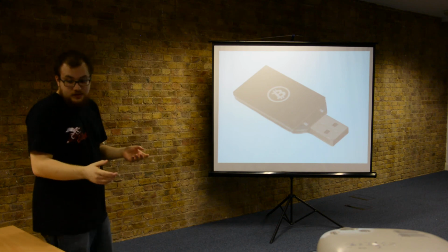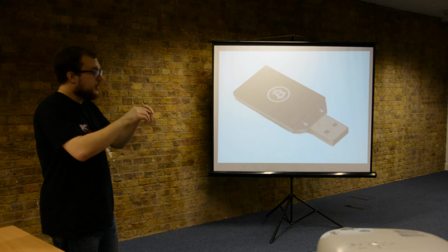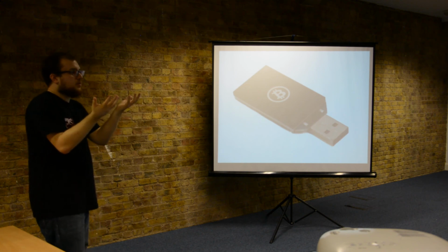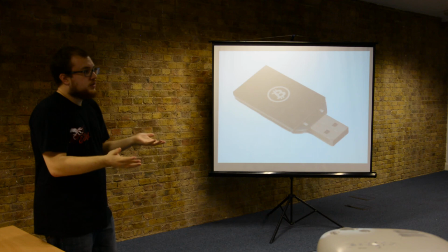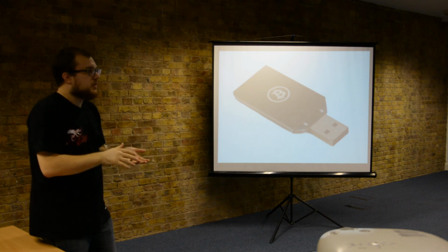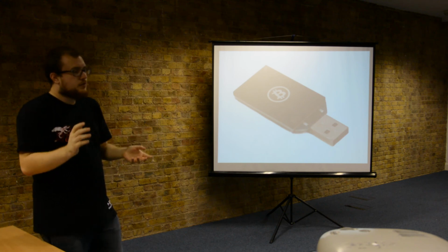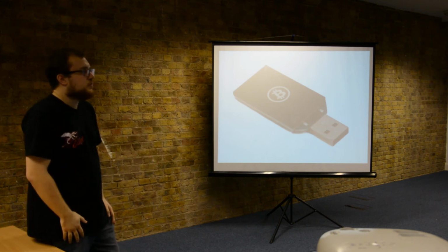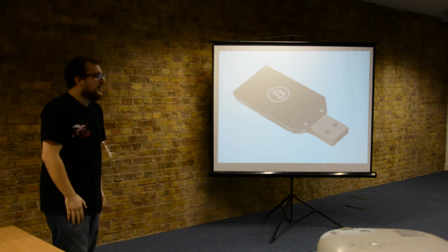If you look at power transistors especially, you'll see lots and lots of tiny holes near them on the PCBs. That's to dissipate the heat onto both layers of copper, or more if it's a multi-layer PCB. But if you overdo it, then it's not good either. Most manufacturers have guidelines on how to design these PCBs, for you to read. They don't design them for you.